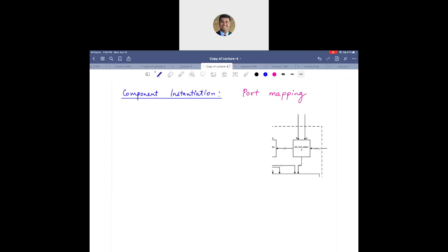I don't think that there is a very easy way to do this. You will have a couple of options. What you can do is pull out those intermediate values and connect them to an LED and monitor the LED getting switched on or off, or you would have to write a test bench. So you would have to write a separate VHDL file which is essentially a simulation of your VHDL design. We call that a test bench. So you can use that to verify how your design is working. So you can do a couple of things there.